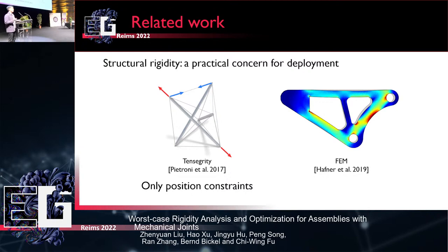And using the finite element method can be quite powerful. You can prescribe the loads and it can compute the stress distribution. But that's also the problem, because we need to prescribe the load. We can do shape optimization on top of it, but prescribing the load sometimes is not very straightforward, especially when dealing with something like toy assemblies or the assembly structure we talked about, to be deployed in a children's playground. You never know what the kids would do to your precious assembly.